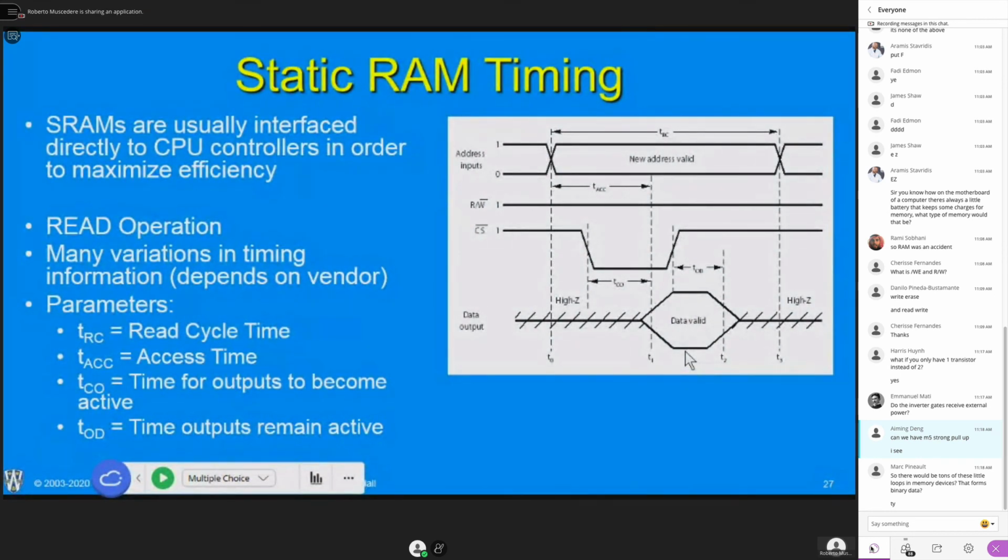And usually slowing down the system is the better option. You have to really look at what your application is. Do I need my system to be operating at whatever speed it is? Not every electronic system has to operate at maximum speed. Usually we pick a speed that's just right for the application, and that's good, because the faster transitions or the faster clock means more power consumption, and I obviously need better parts to keep up with that.